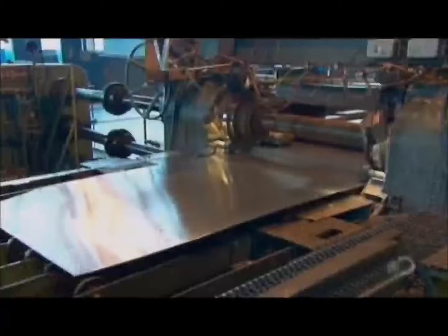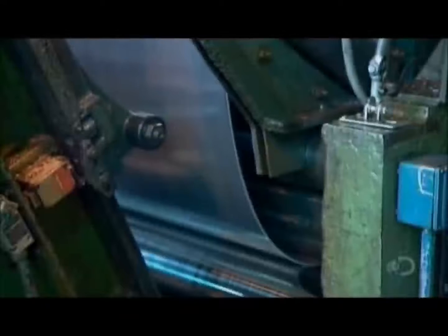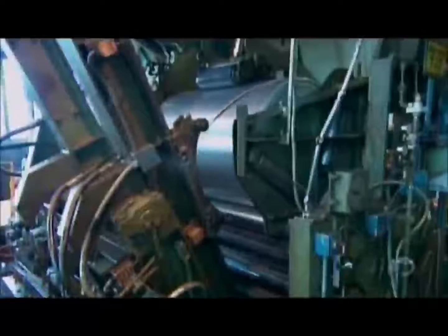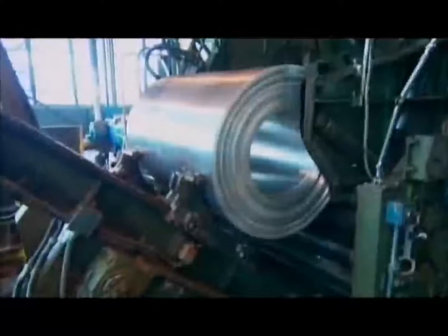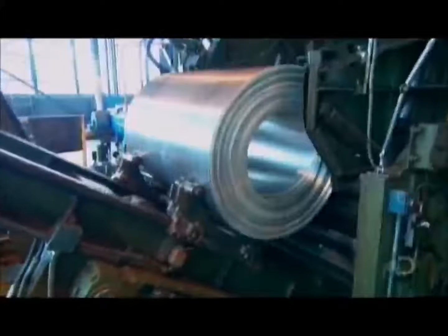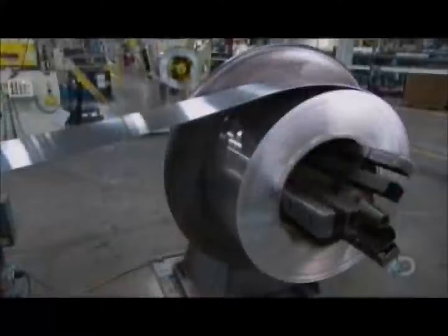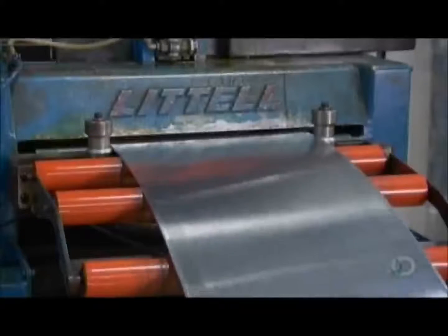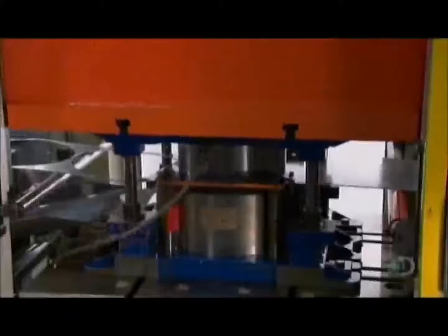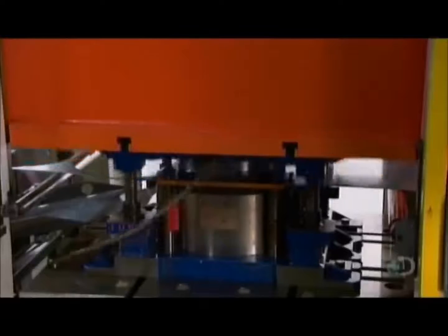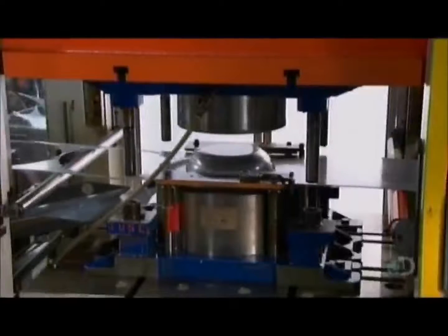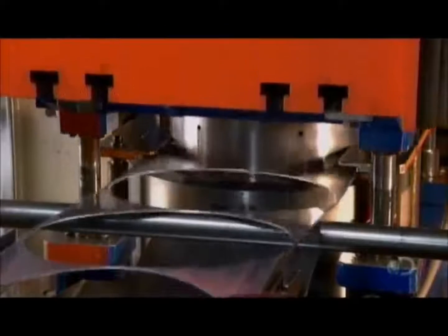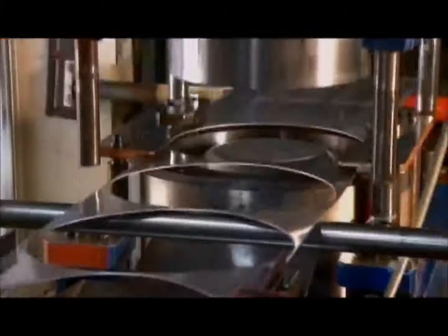Next, again the edges of the aluminum sheets are trimmed. After the rolling process, the slabs become sheets. Another roller winds the sheet into a big coil. Next, it is unwound to flatten. The sheets are pushed into another machine where they are pressed using a 120-ton punch press, which is the forging process. This shapes the aluminum sheets into a frying pan shape.